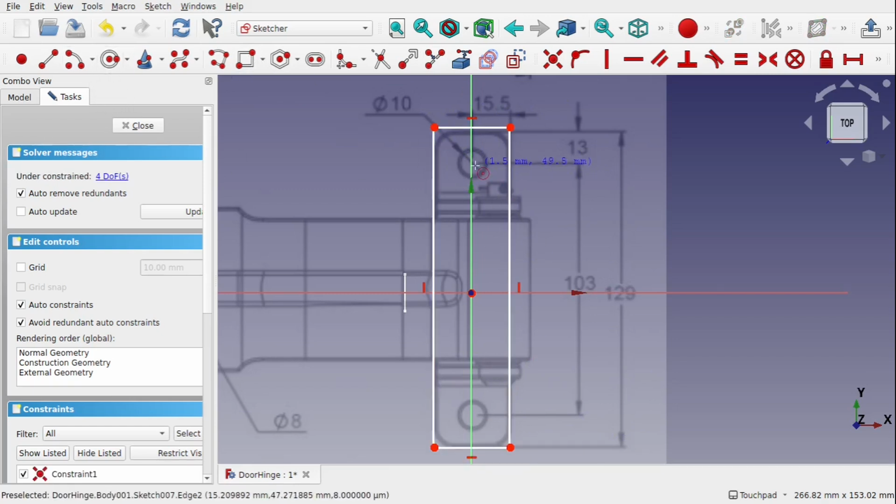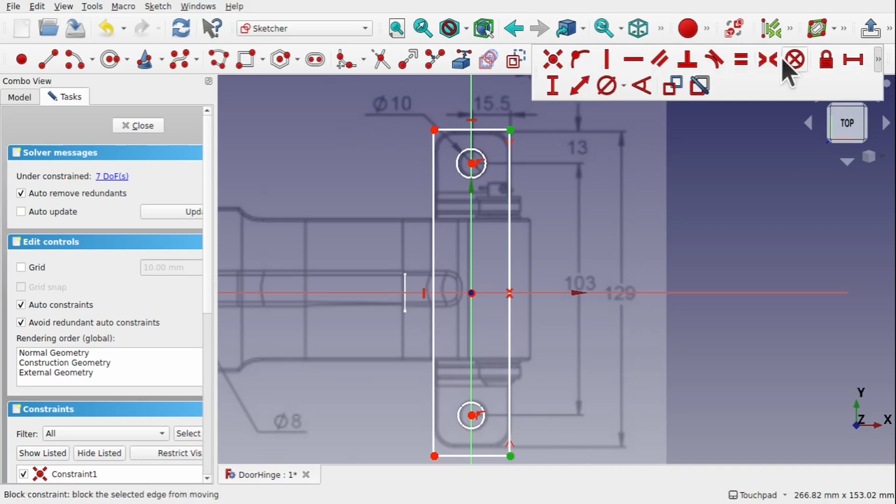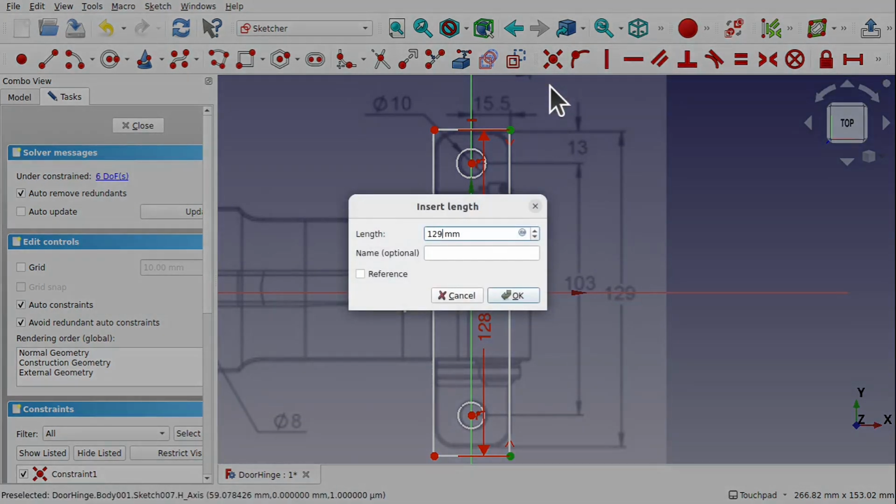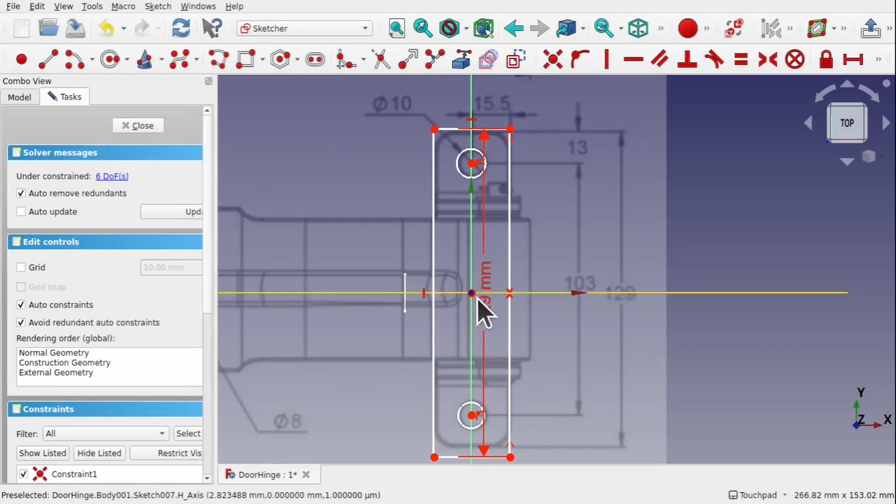We also need a circle. Connect that to this line to create the circles in here. So we've got those. That's create the distance between these two. Now this is span distance, so this is the reason why we placed it across the middle, because we can take those 2 points and use the x-axis and use the symmetrical constraint, and then place a distance between these two of 129. So height 129, or we can just select this line and place 129 in there.